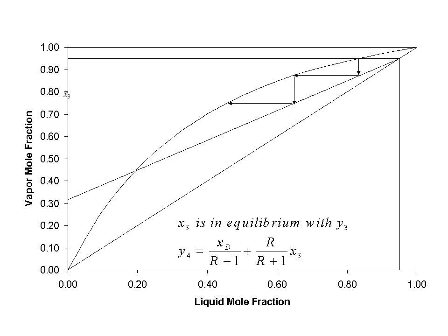And now that x3 is known, we can determine Y4 by looking at the material balance and using the operating line equation, substituting in the value for X3. And this procedure can be repeated above the feed stage until we get to the feed composition.